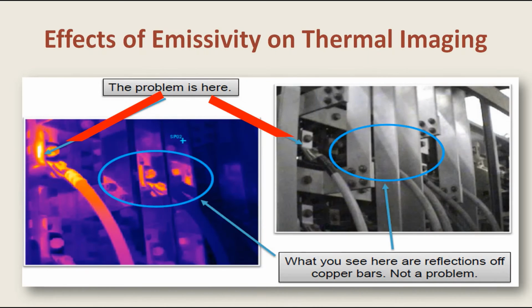It is important to understand that the object's temperature cannot be calculated by just measuring its emitted infrared radiation. It is important to gain knowledge about the emissivity of the object. An object with high emissivity will appear hotter as compared to an object with low emissivity when placed together under the same conditions of temperature, moisture, and other environmental conditions.